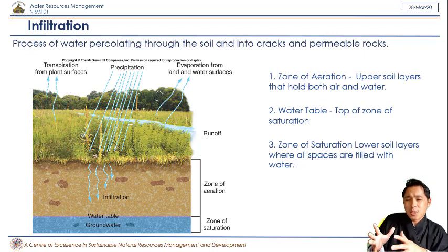These zones are saturated with water, and the saturated zone has a line that divides it from the unsaturated zone. That line is what the water table is all about, where the atmospheric pressure and the pressure on this water are equal. So that's the water table. The distribution of aquifer materials is all throughout the zone of aeration and even through the zone of saturation.